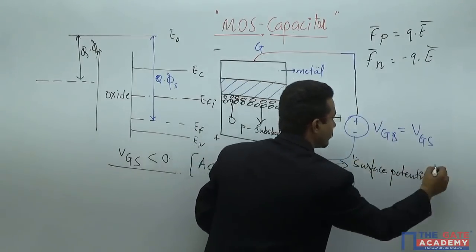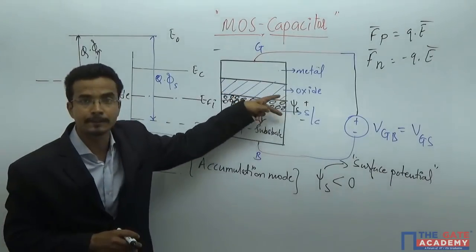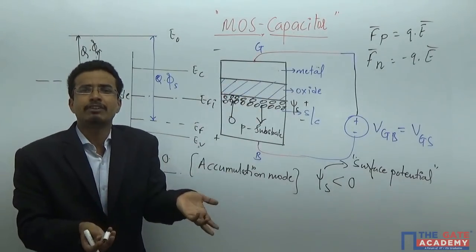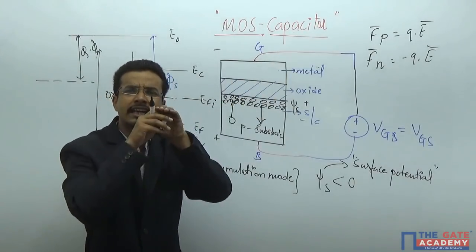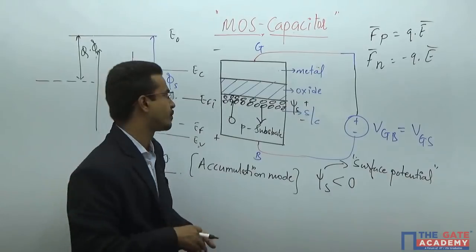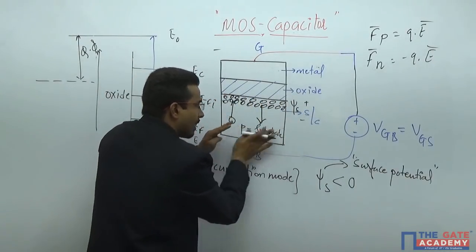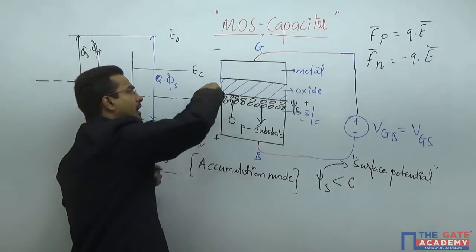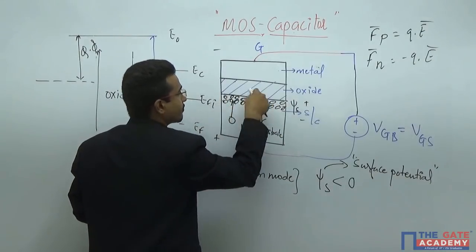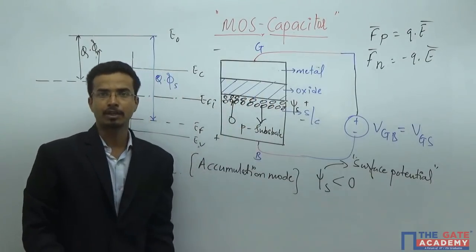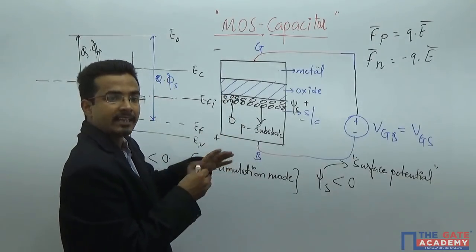What is happening with the charge carriers across this particular junction? Whenever you go into the detail of MOSFETs, all the conduction parameters are just because of these charges. So I am not interested in the entire bulk. I am interested only in what is happening across this junction, at the interface of the oxide and semiconductor, because the entire electrical behavior of this device will be decided by that only.